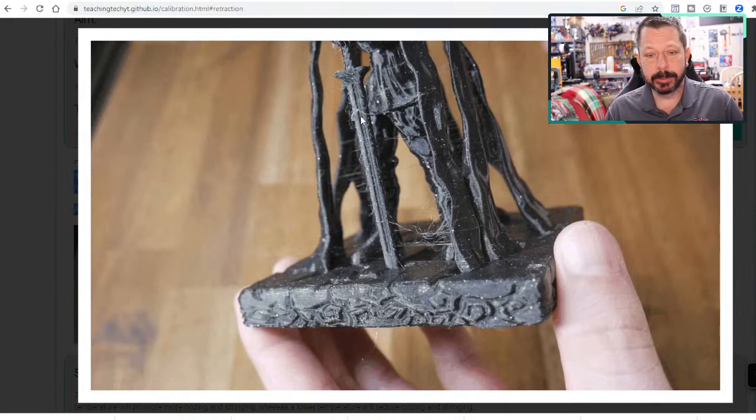You have to be careful though, because the glass transition temperature for PLA, when it becomes formable, doesn't necessarily melt, but it becomes softened, is only like 65 degrees Celsius. So it's 150 whatever degrees Fahrenheit. And you can easily deform your models with a heat gun. Even a hairdryer can do that. In fact, there are some models where that's specifically the point.